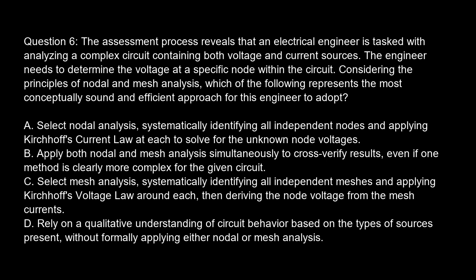Option A. Select nodal analysis, systematically identifying all independent nodes and applying Kirchhoff's current law at each to solve for the unknown node voltages. Option B. Apply both nodal and mesh analysis simultaneously to cross-verify results, even if one method is clearly more complex for the given circuit. Option C. Select mesh analysis, systematically identifying all independent meshes and applying Kirchhoff's voltage law around each, then deriving the node voltage from the mesh currents.